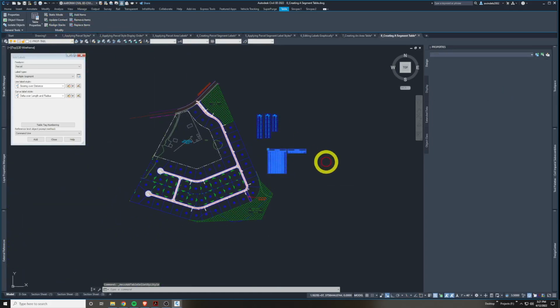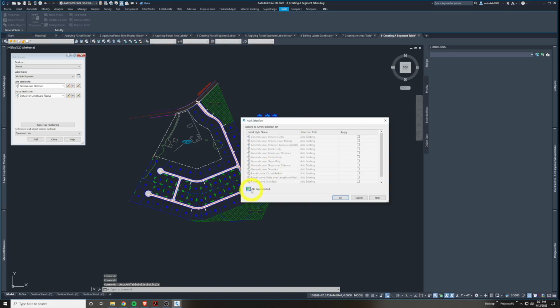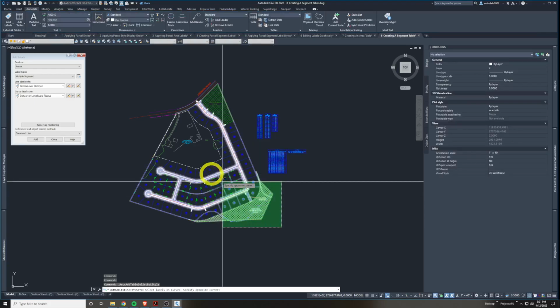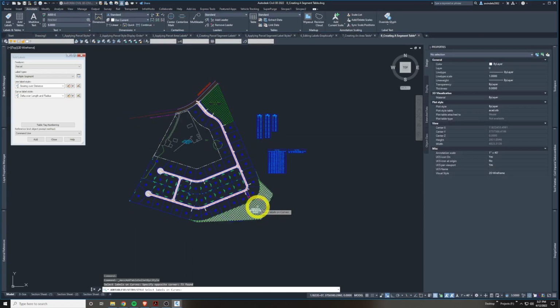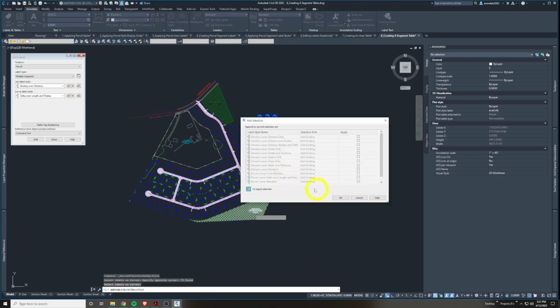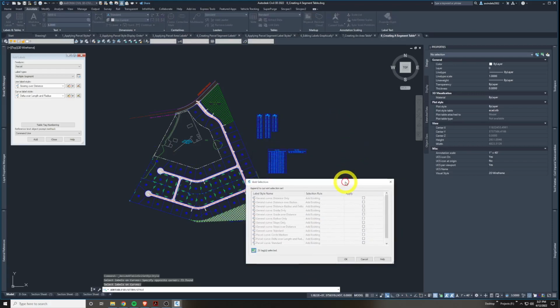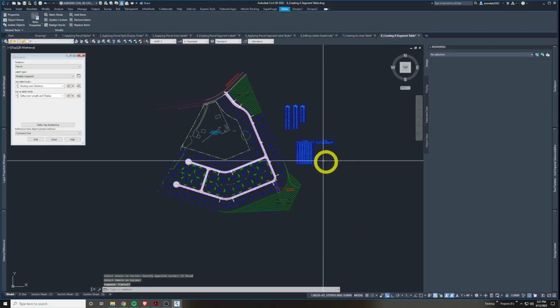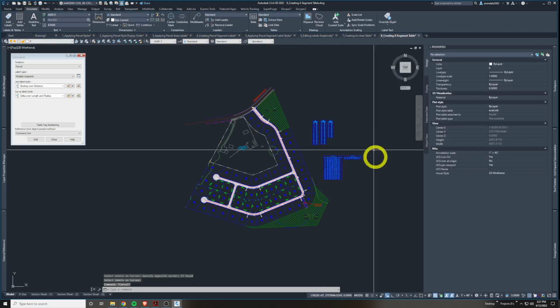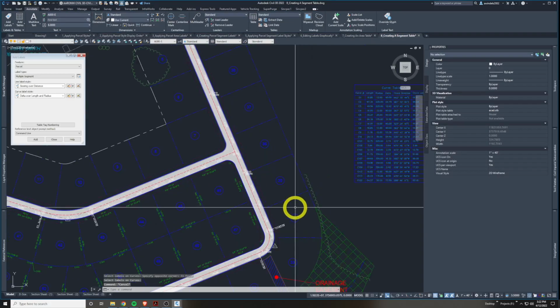Now, if I wanted to add even more, I might just use this button. Let me pan over the whole thing so I get them all. Hit enter. It found 21 of them. Let's see if it adds any more than 21 here. I'll hit OK. Looks like I got them all. So that's the end of chapter 13. We learned a bunch of ways to further edit parcels.